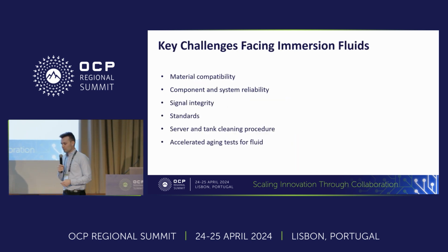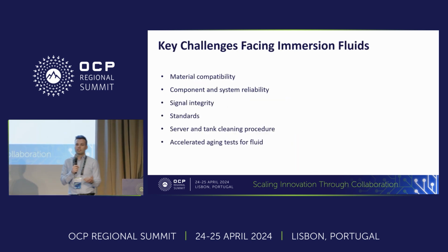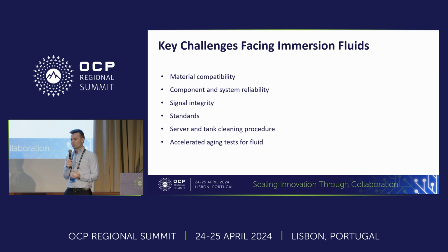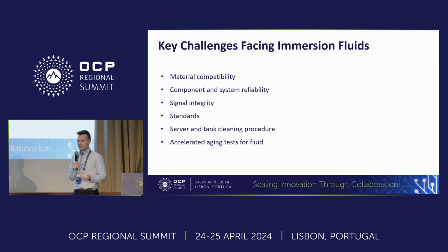I gave a presentation in Prague last year at the regional summit, talking about some of the key challenges facing immersion fluids. A lot of you will be familiar with these as well. We had material compatibility, component and system reliability, signal integrity, standards, server and tank cleaning procedures, and an accelerated aging test for fluids. These are just some, and we can go on and on about all the different challenges.